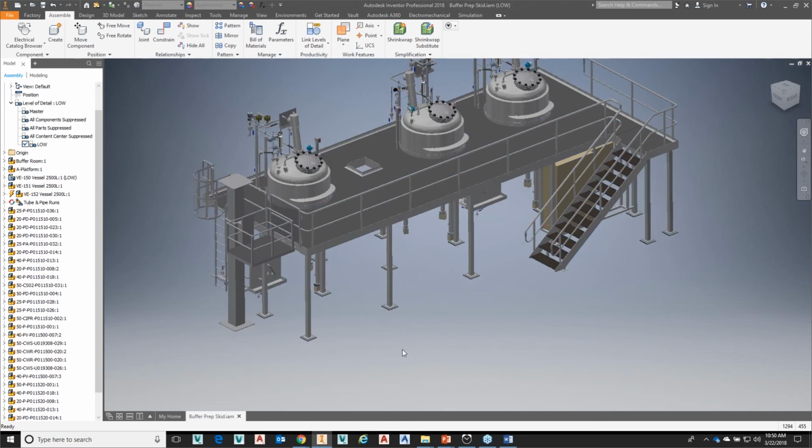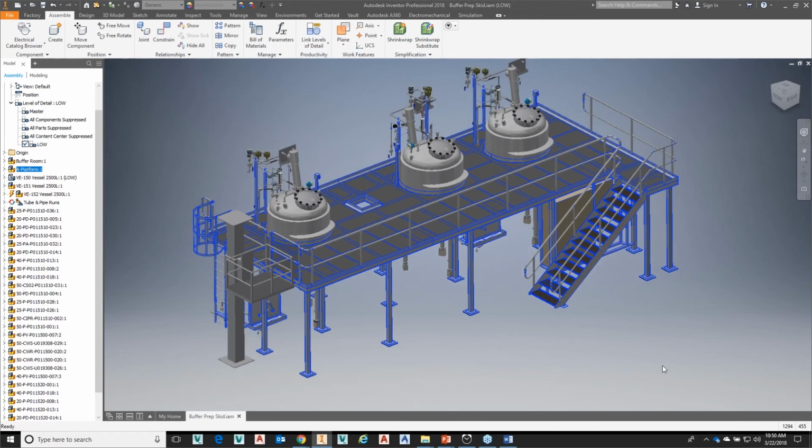Yep, and you lost almost 200 parts there. Yeah, I only took a minute to take one subassembly and create those low level of details. If I had done that here and here and here at the platform, then I could easily lose a lot more in terms of count here. That'll open up much faster. Okay. So a caveat here with levels of detail. Okay. People will go crazy and create lots of levels of detail.